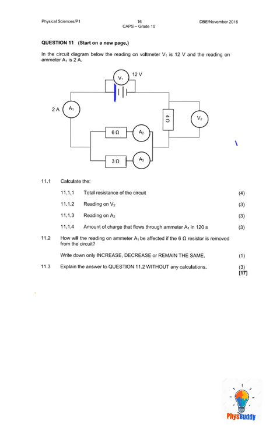The longer line here at the battery shows the positive terminal, and the shorter line signifies the negative terminal of the battery. And we know that the total current in the circuit starts off at the battery, and it would then flow through this ammeter. So this tells us that this ammeter measures total current. That's the total current as it leaves the battery, and they've given us that. They said it was 2 amperes.